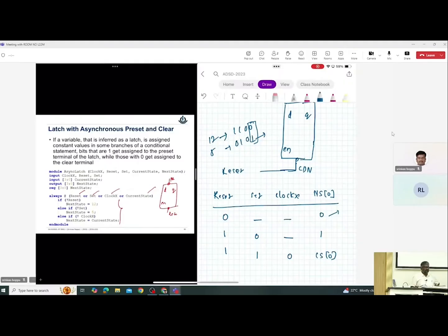Okay, good. Since we have only the CDN pin, the output is set to 0, and now we connected this one, which means we have completed this entry. Now what is left? We are left with these 2 entries. In these 2 entries, what should we do? We have to make the latch open.